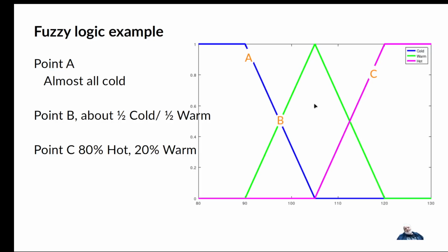Now when you set up fuzzy sets like this, you can use nice straight lines that make triangles or trapezoids, or if you really wanted to, you could use some kind of curved thing, usually they refer to it as a Gaussian curve, a nice smooth curve. However, when you're going to implement this inside of a computer, especially a small microcontroller type computer, you really want to implement this with straight lines, just because the amount of compute effort is very, very simple.